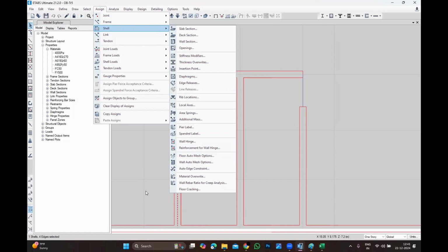For example, I do have a precast wall. In precast, there are two options, right? One is a load bearing structure, another one is non-load bearing. Most of the load bearing walls, about 70-30, 70% I mean, look like a wall, 120 millimeter, 150 millimeter, 160, 200. Actually, 70% of them are not a wall. When you check the detailing, it has a top bar and bottom bar, and the vertical ones are links. It's a deep beam. It's a full height deep beam.